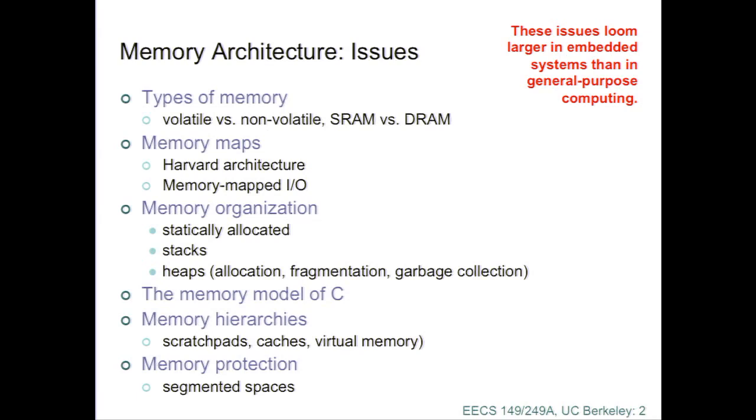But in the case of embedded systems, it's very often not the case. Well, first of all, you have to grapple with the fact that you don't have an infinite amount of memory, okay? You also have to, one interesting twist with embedded systems is that you care a lot about how the system behaves over very long periods of time. There's lots of embedded systems where rebooting is unacceptable and you want to run for years, okay? So you can't afford to just keep allocating memory and never deallocating it, okay? That doesn't actually work because it'll cause your system to crash at some point.